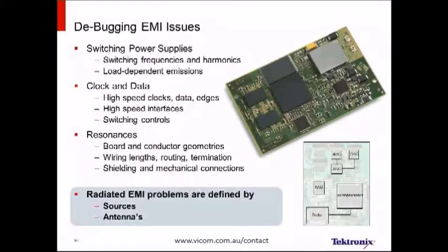Second to switch mode power supplies and switching circuits, I often look at clock and data. Depending on the design, you may or may not be employing some form of spread spectrum clocking. It's important for us to know how well our spread spectrum clocking is working. After that is looking at a broad term I call resonances. Resonances could be actual in the board itself. It could be into wiring geometries. It could be into cabling, shielding, and mechanical issues.